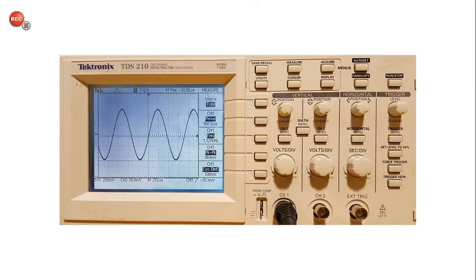And so this is what the oscilloscope looks like. These are the settings that the channels are currently set to, along with the seconds per division setting, and we can calculate the peak-to-peak voltage or the peak voltage and the period and the frequency of the waveform just by observing the screen. The oscilloscope also does those calculations for us.